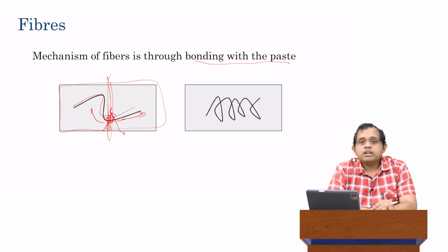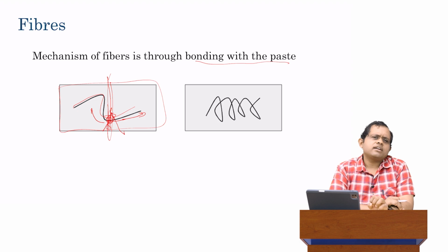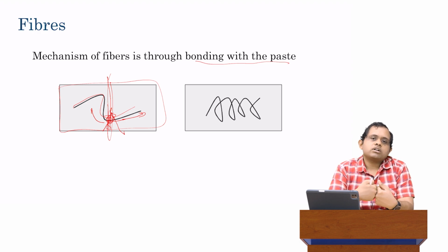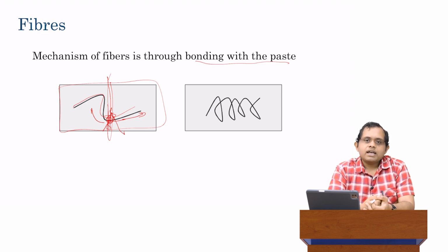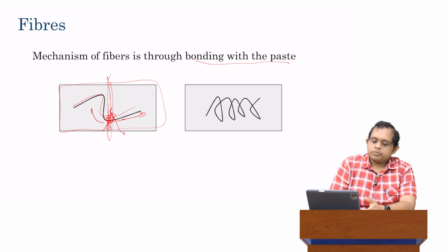Now, it could be relieved, for example, by complete breakage of the fiber, that the fiber could split into two because it's being pulled apart. That's generally rare. These fibers are very, very strong in tension, so it's very difficult for that to happen. It eventually happens because whatever this tension is, it tends to exceed the bond strength of the fiber, and so you tend to have what is called a pull apart or a breakaway sort of failure. So let me just draw this formally.